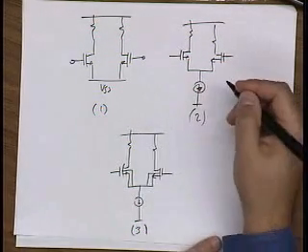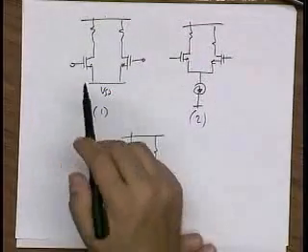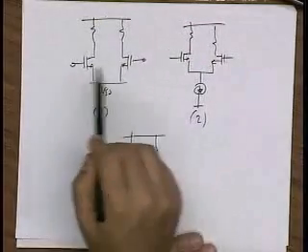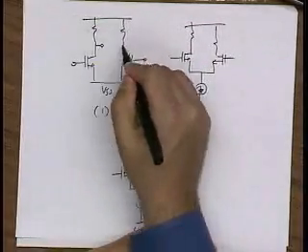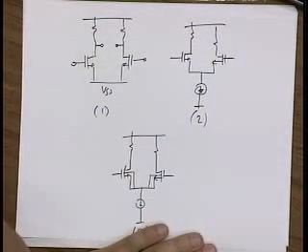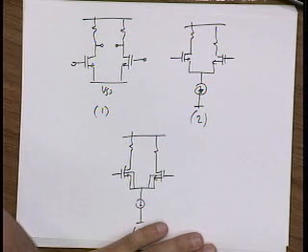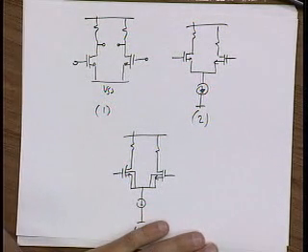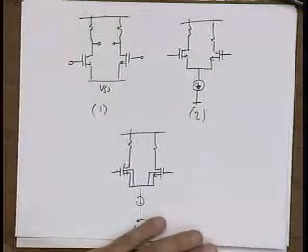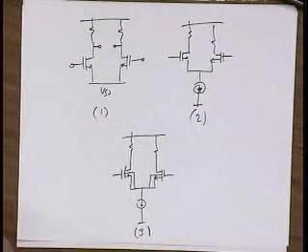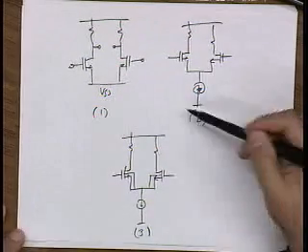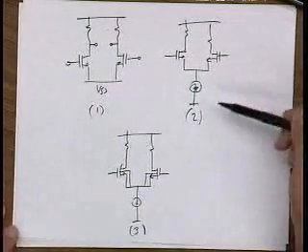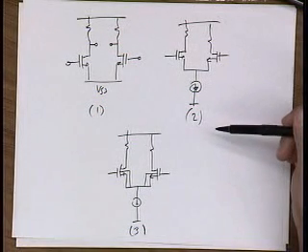So first of all, let me ask you a simpler question. What's the common mode? If I apply a common mode signal to this guy, what differential output mode do I get? Okay, 0, right? That's pretty good. That has infinite common mode rejection. But why is it that everybody uses this circuit, even though it has basically headroom issues?